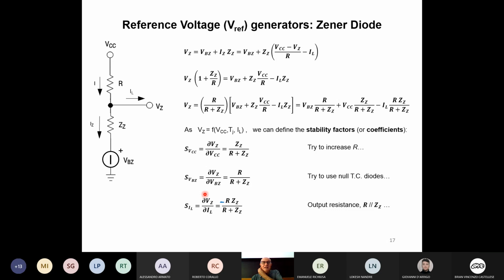So what can we do? We said that the resistance R will go up. What is left for sure is the dynamic resistance of the diode. And we cannot do anything about this. When we buy one diode, the dynamic resistance that we'll see will be the dynamic resistance of the diode. So once we buy a diode, we cannot change it. The only way to reduce the dependence of the output voltage on the current is to decide that we don't take any current from this voltage generator.